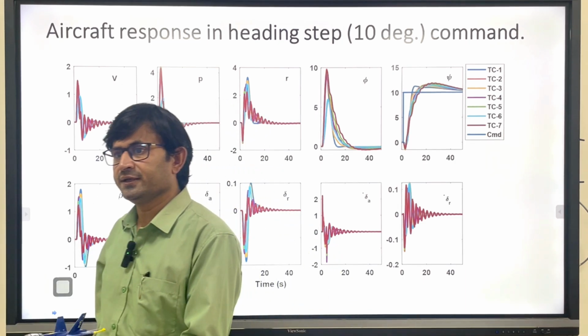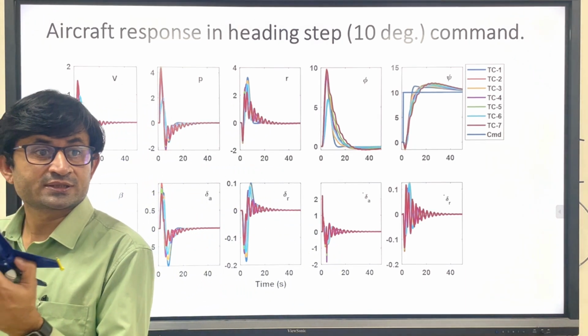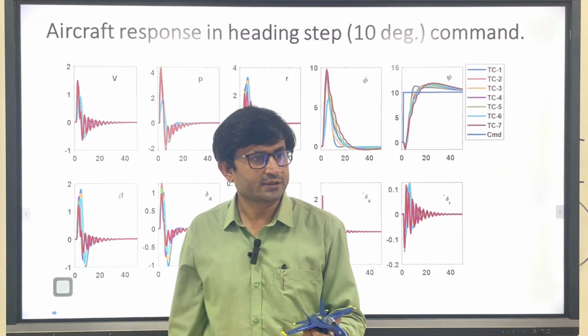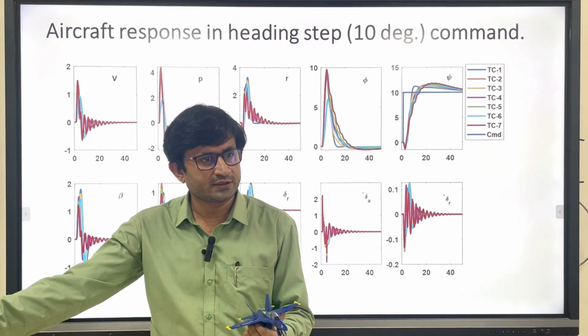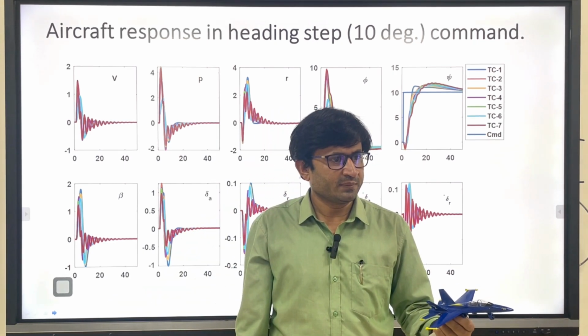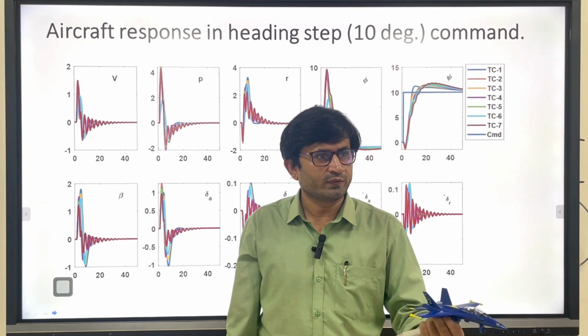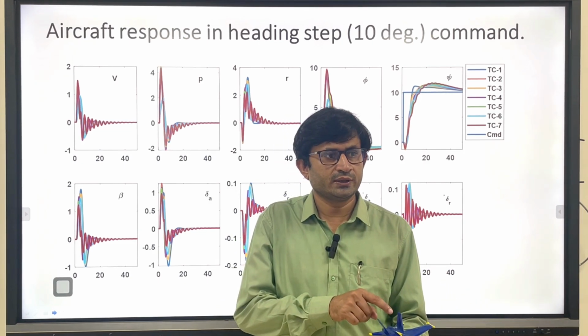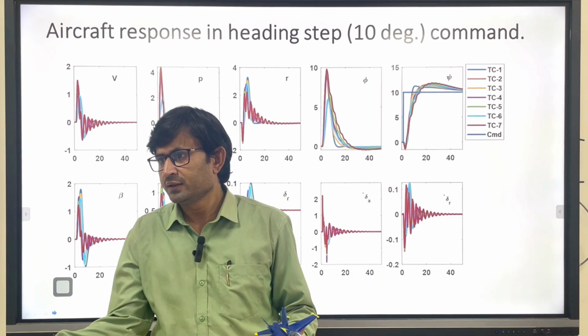You should not skid and you should not slip. Skidding means you are going away from the radius of turn, and side slipping means you are moving forward and also moving laterally. That means you are not actually taking a turn towards the center of the turn.